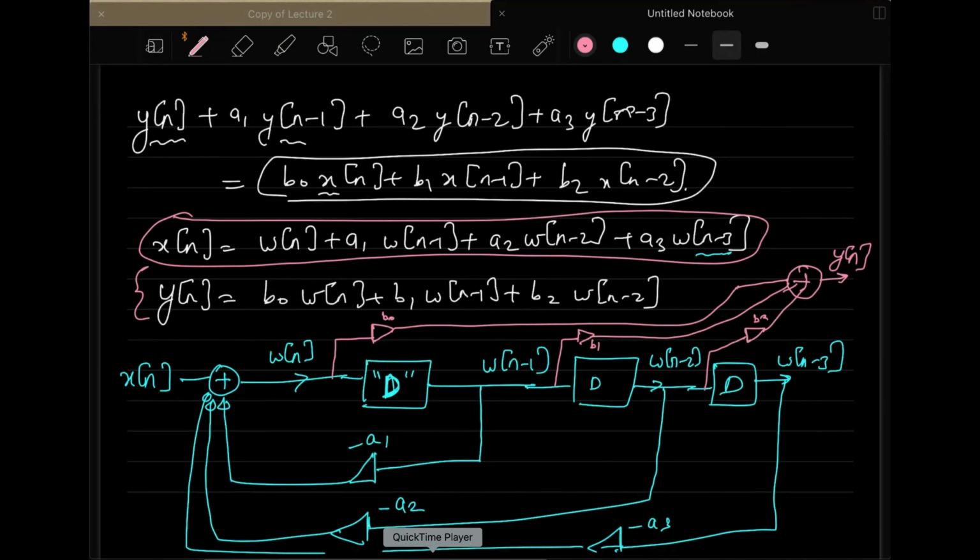So again, a point to be noted here is that if you have initial conditions along with this, as we had discussed in continuous time in much detail, if you recall that, then the initial conditions will be in the form of like this, like you'll have y[minus 1] equal to, let us say, 2, then you have y[minus 2] equal to 3, like this you have some initial conditions, or y[plus 2] equal to, oh sorry, not plus 2, it will be minus only.